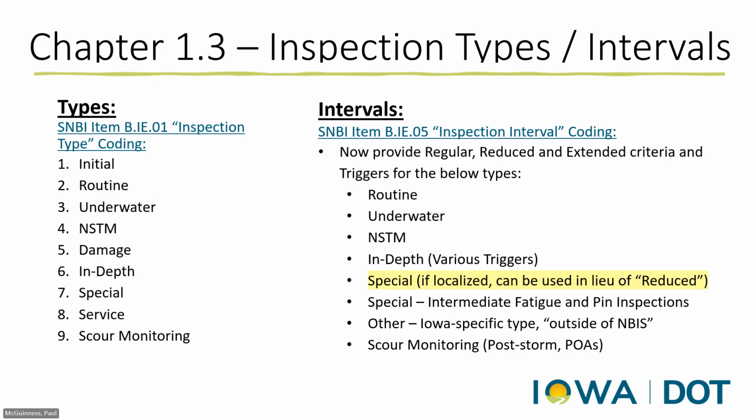And once you hit 6 feet, boom, you need a diver. The interval for these inspections is typically 60 months. Again, if conditions are poor, we can reduce that. If conditions below the water line are good, we can actually stretch that to 72 months.